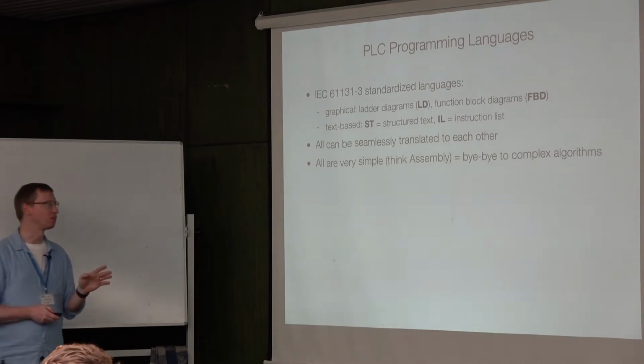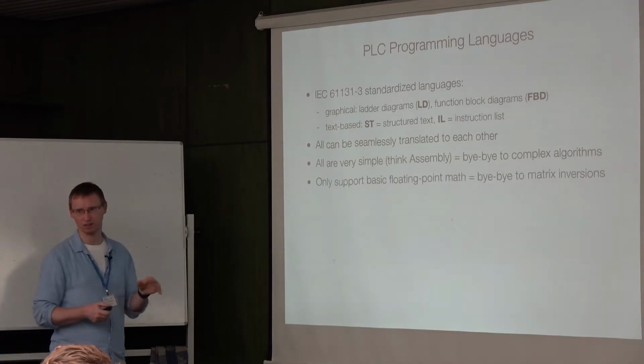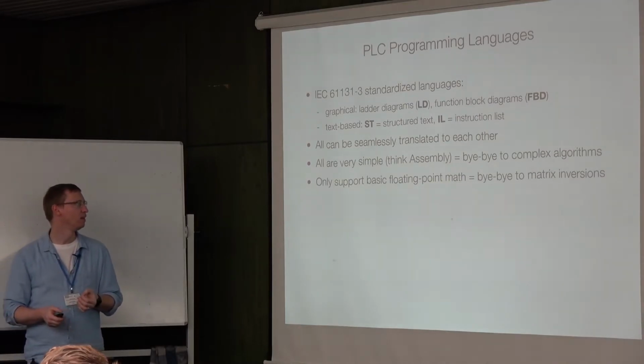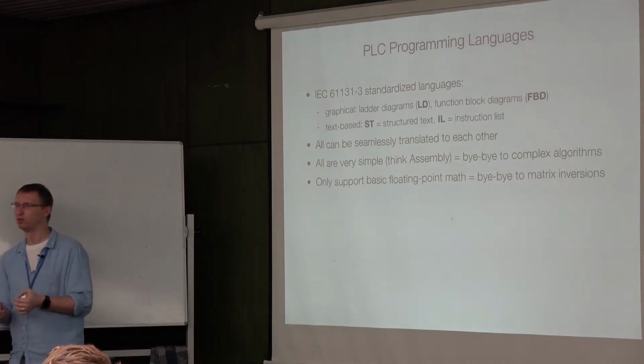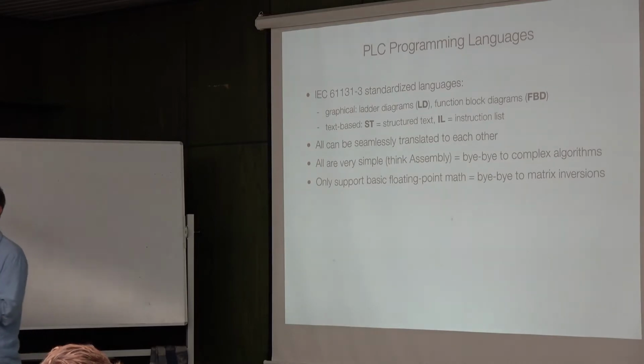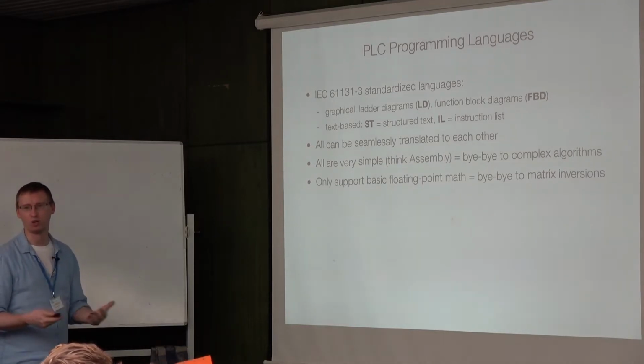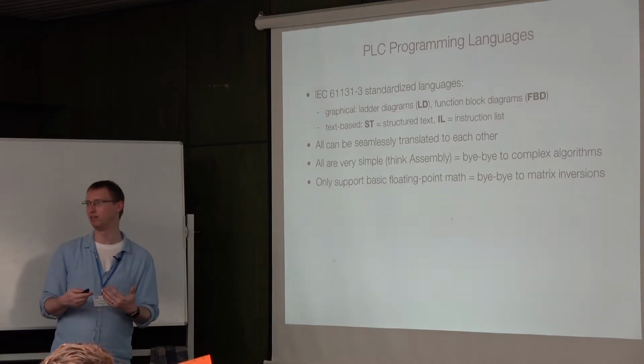However, there are some PLCs that do support, say, C code programming, where you could use these algorithms, but in general, no. I mean, even anything beyond simple floating point math, like division, maybe square root is the pinnacle of what PLCs can do. Basically, we have to restrict and keep our algorithms to be very simple.